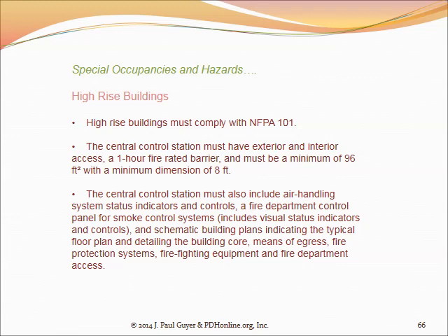And the detection system in a high-rise building, typically the way it works is there are, of course, fire detectors on all floors, and one of the things that the system does is send a signal to a control panel, a fire control panel that's typically located down at the first floor, either on the outside of the building or on the inside of the building in the stairwell.